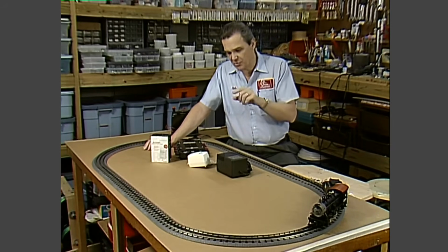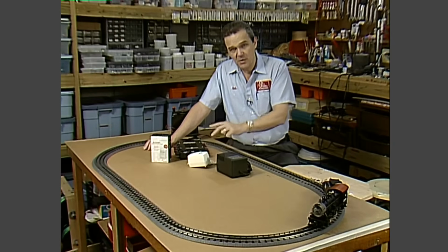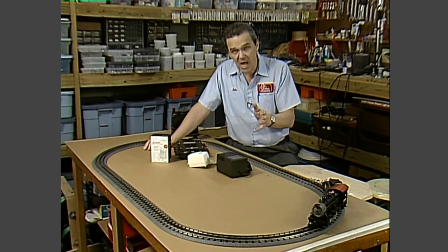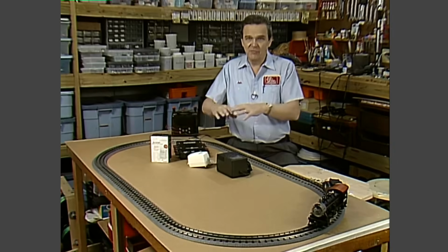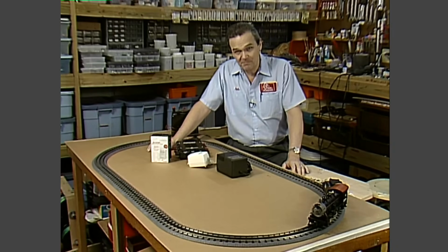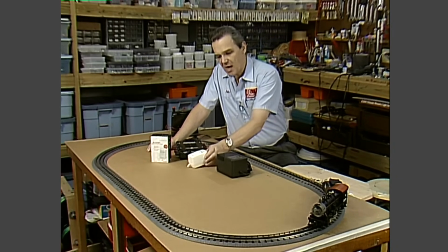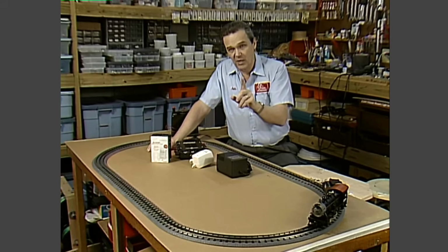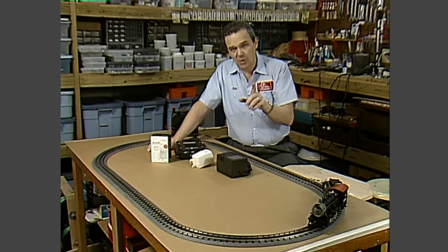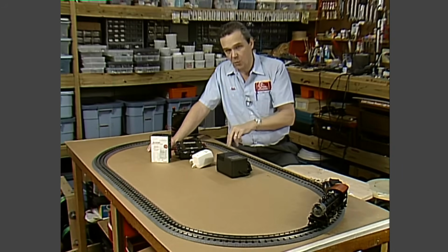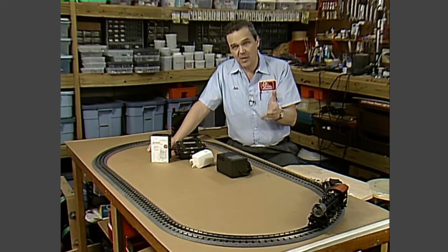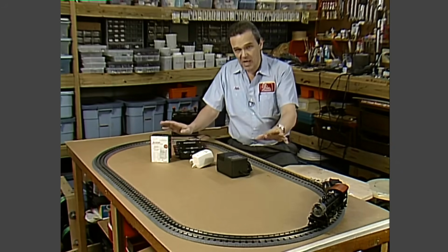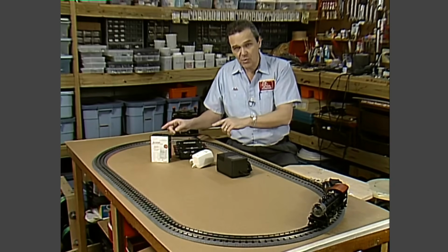In addition, if you're using the variable output channels on the TIU, they shut down. So any trains running on those channels will stop too, whether you want them to or not. In this situation, getting everything reset back to normal can be a real problem. However, if you power the TIU from this jack with a separate small transformer, you will always have control over the layout no matter what happens. If you get a short that trips a breaker in a transformer feeding the fixed in 1 channel, the only thing that happens is the track power to that section of the railroad shuts down. The TIU itself is still running, and you still have control over any trains powered by other TIU channels.